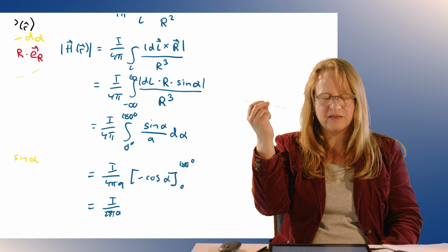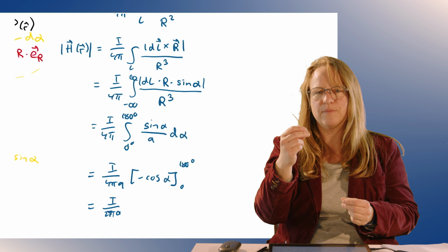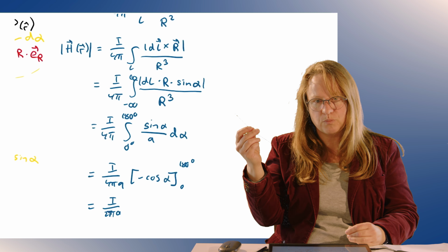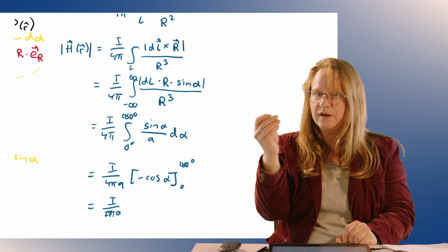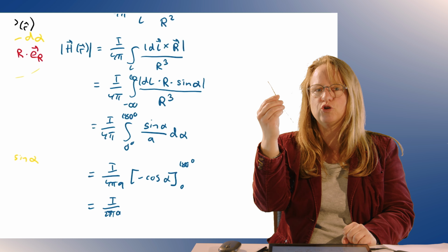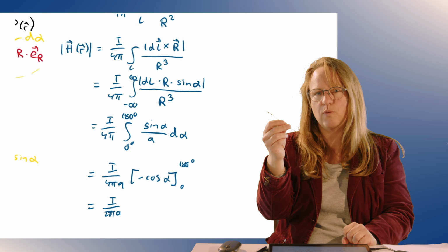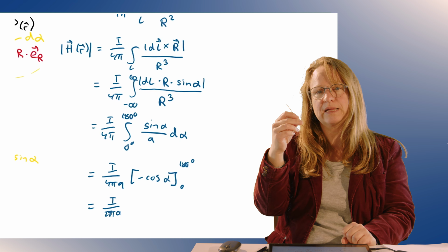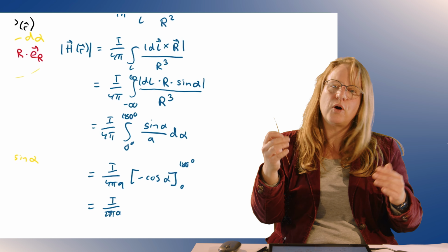So it might seem trivial that you have this one small piece of wire and now you can calculate the magnetic field. But think of all the printed circuit boards, all the different circuits you have. With this piece of information, that you can calculate the magnetic field at an arbitrary point around an arbitrary length piece of wire, you can, by the superposition principle, calculate all the other situations. Of course, we do have a bit of a problem in magnetic materials if we are going towards materials with hysteresis effects, nonlinear HB relations. Then we have to see how the superposition principle holds. But this is not the topic today. Today we just looked at this one piece of wire.